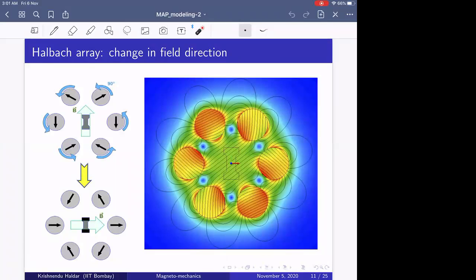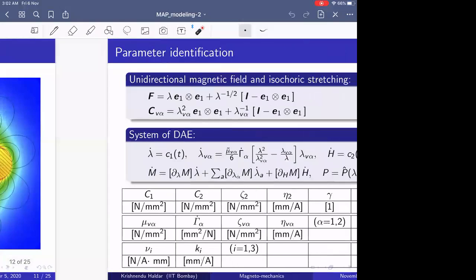But once you put this magnetic material in, it becomes magnetized and will have its own magnetic field, which is known as the stray field. So what you are recording as your magnetic field, like 0.43 Tesla, that is your applied magnetic field, but it is not the actual magnetic field inside any material point, because it will change due to the demagnetization effect.